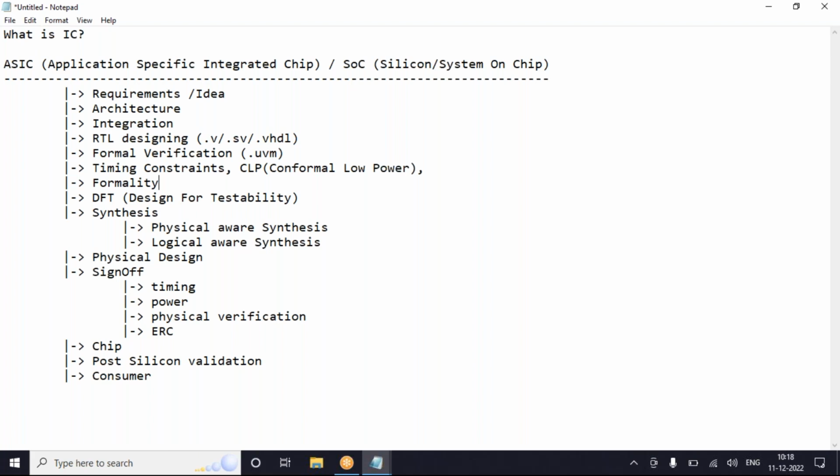That means your RTL code to synthesis code to PNR code. Very long codes I'm talking about. RTL is a behavioral code and synthesis is a converted code. Those need to be verified, whether it is properly converted or not, and whether any connections are missed. I need to check pin to pin connections. That will be done using this formality. We will be having dot V checks.